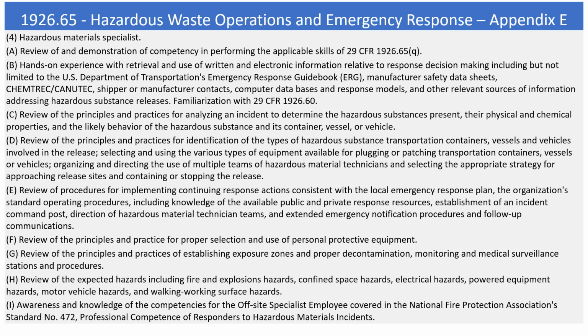G. Review of the principles and practices of establishing exposure zones and proper decontamination, monitoring, and medical surveillance stations and procedures. H. Review of the expected hazards including fire and explosions hazards, confined space hazards, electrical hazards, powered equipment hazards, motor vehicle hazards, and walking working surface hazards. I. Awareness and knowledge of the competencies for the off-site specialist employee covered in the National Fire Protection Association's Standard No. 472, Professional Competence of Responders to Hazardous Materials Incidents.